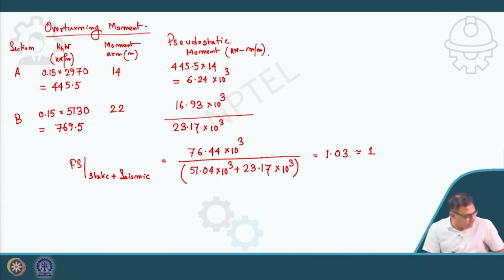But one more thing, when we are talking about how to calculate this considering the pseudostatic analysis, it is a very simple analysis, but it has some limitations also. The limitation is that the time dependent effect is not considered. Even in some cases it has been observed that the pseudostatic analysis shows the factor of safety is adequate, but still the structure failed. So, that is why